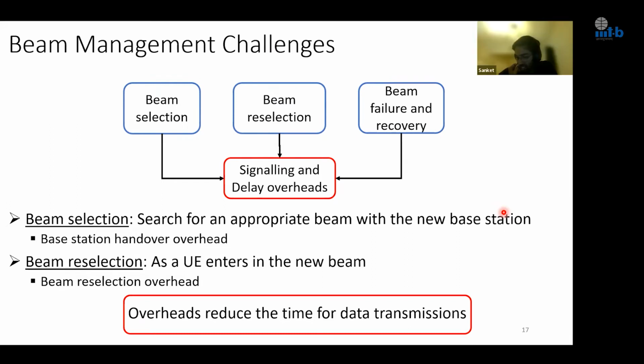Oh yeah, that's a good question. Technically, there is no challenge in using beamforming even at lower frequencies. I don't know about 700 and 800 megahertz, but if we go to sub-6 gigahertz frequencies, which 5G is also going to use, it is possible to use beamforming. As I will show in the numerical results, we did the analysis for both sub-6 and millimeter wave. But the beam management problem is more challenging, or more interesting, for mmWave because in mmWave we have very high attenuation, right?